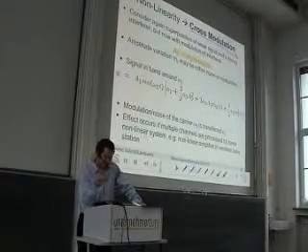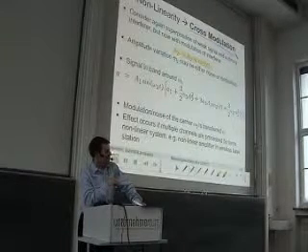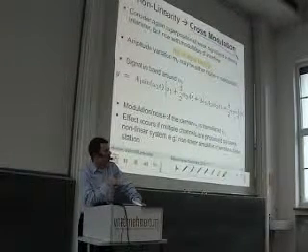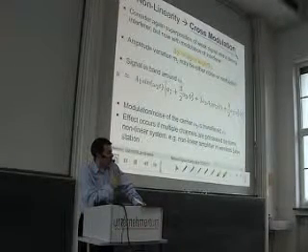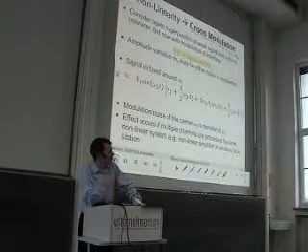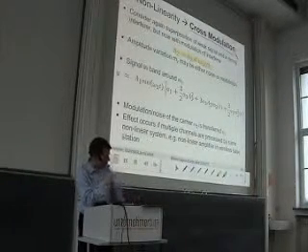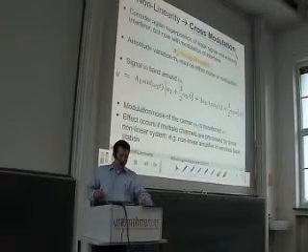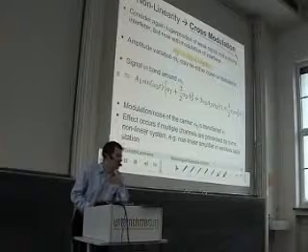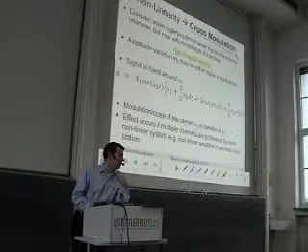If one signal disturbs the other one, then it is desensitization. Or if the information from one channel leaks to the other one due to the same effect, then we talk about cross modulation. And these are lots of unwanted effects that we have here, which are purely caused by the nonlinearity of the system.